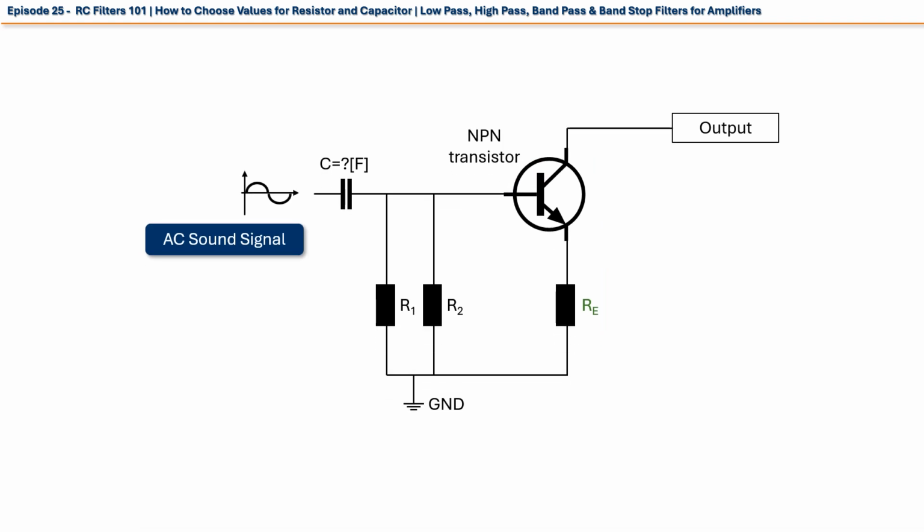Now, there is only one more job to do, and that is to solve the problem of voltage drop across the base emitter junction. If you have watched our videos, you know that there is 0.7 volts of voltage drop across the base emitter junction. We have also explained and demonstrated how this voltage drop can be represented with an equivalency diode, and then this diode can be substituted with an equivalency resistor, called re. This internal resistor should not be confused with the emitter limiting resistor with a similar name. There is one more for the book of idiotic naming schemes in electronics.